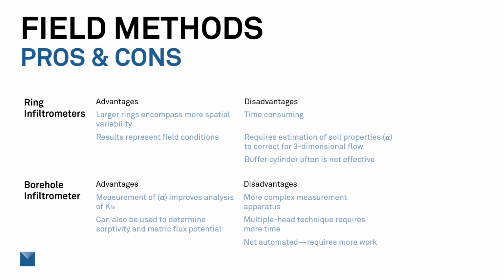Some of the disadvantages with the borehole infiltrometer is they're typically a more complex apparatus to set up and to get going. It does require a little augering and those types of things. So you do have to be careful with that. If you're using the multiple head technique, it is going to, again, require more time to actually take the measurement.